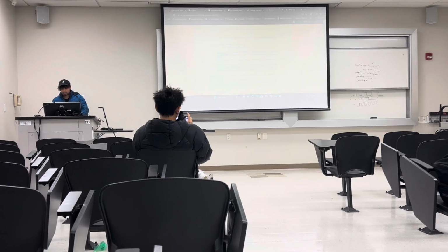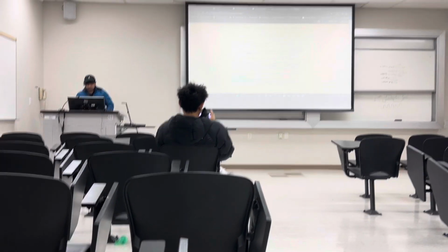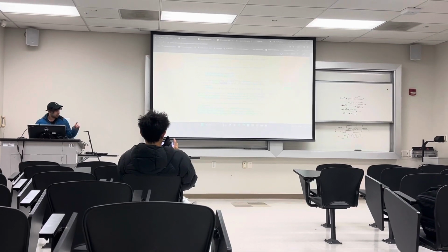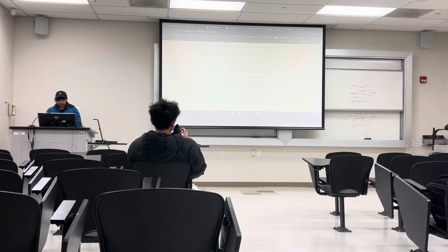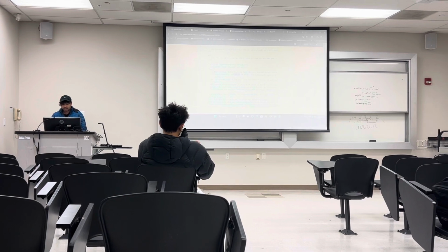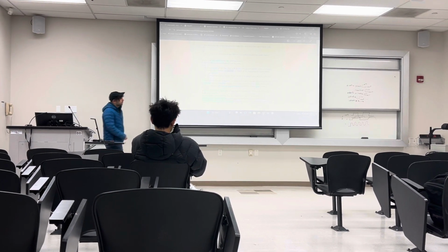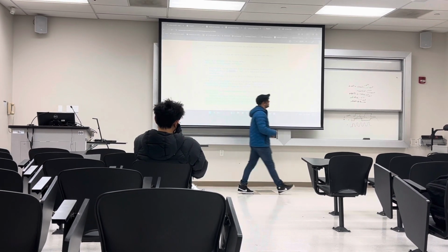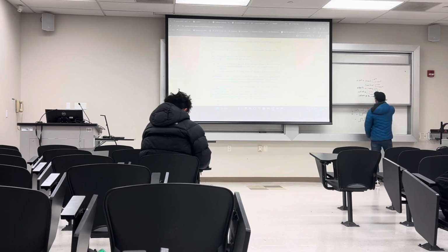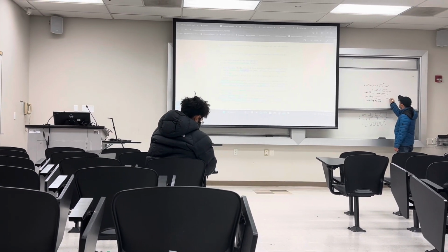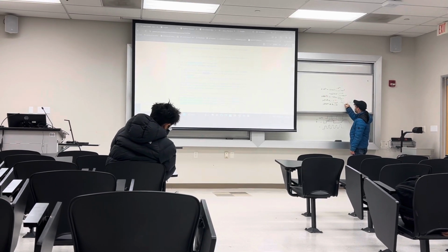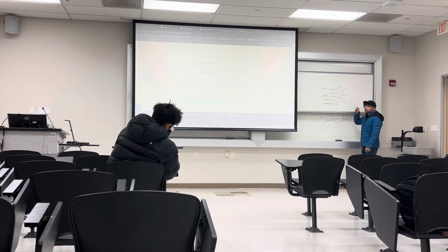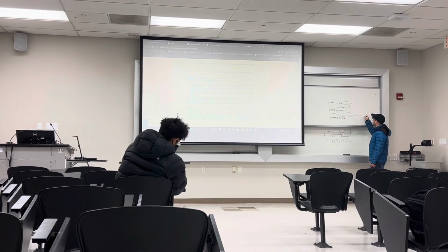Okay, after you output the waveform, design the layout. So I showed you how to design the layout of this JK flip-flop based on the circuit that you had, with DRC, LVS, and parasitic simulation. After that, you need to pass the DRC of this layout, then LVS, and take a screenshot of these two. And then you also need to run the parasitic simulation again, post layout.